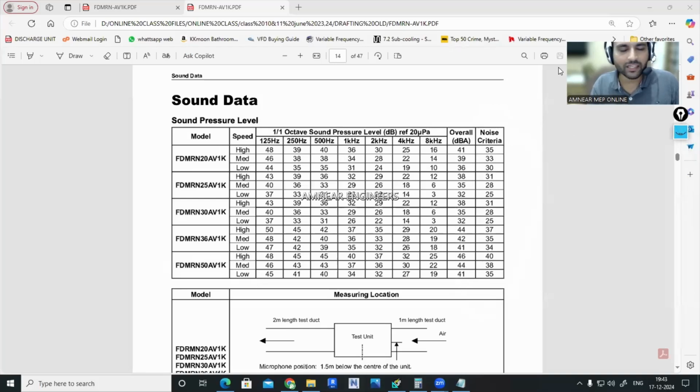Okay, so this is a common concern. Normally, most of the students were asking what we have to do to adjust the airflow rate within HAP. By adjusting the supply temperature, the safety factor of sensible coil load, and the room set point, we can increase or decrease the airflow rate. But remember, 1 ton 400 CFM is a thumb rule.